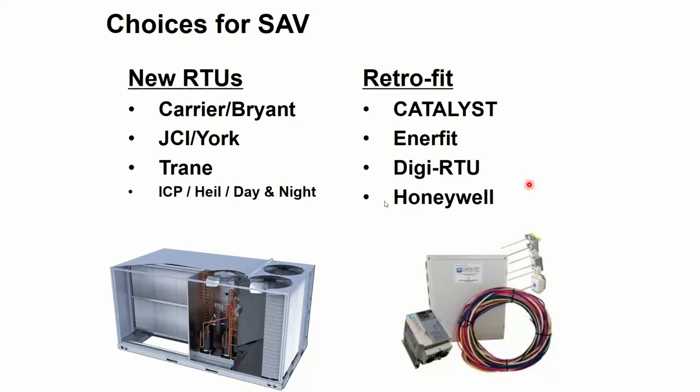If your hospital has constant volume air handlers with reheat coils and no zone dampers, that's when you have to be a little bit more cautious. If it's a hydronic reheat coil, not the end of the world. If it's electric reheat coils and you provide less airflow, you're going to trip out those heaters. So those ones you'd have to pay attention to, and you might not be able to do it, or maybe you can't do it as much. Maybe just slow it down from 100% airflow to 82%. That's all you can do and still have enough airflow for those heaters.